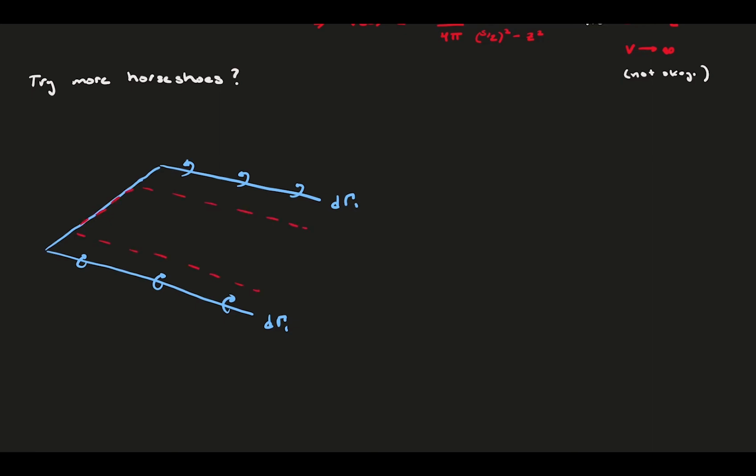In reality, downstream of a foil is a vortex sheet that is shed at the trailing edge of the foil along the span, and those tend to roll up into littler vortices between the major ones. So, in essence, by adding in multiple horseshoe vortices throughout the wake, we're doing better at following reality. And it's also convenient because it will eventually fix our problem.